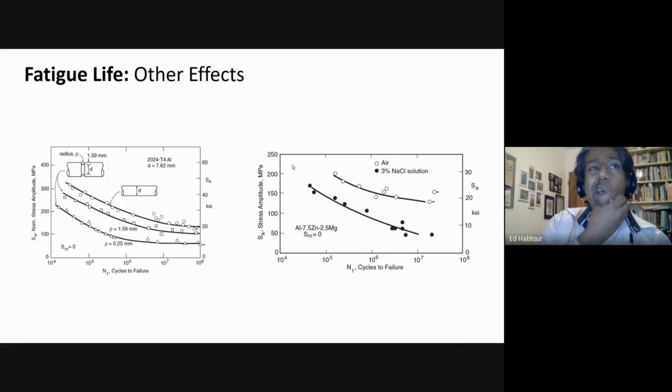Okay, we talked about the effect of the variation in the mean. Now, if there is some kind of a hole or some kind of feature, like an opening for an O-ring in the material, that will also shift its SN curve, rather.